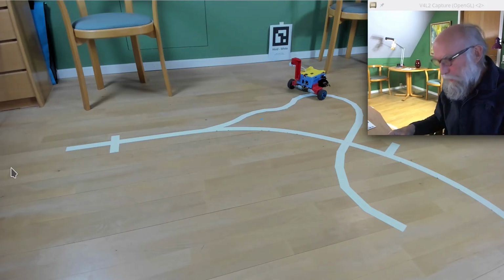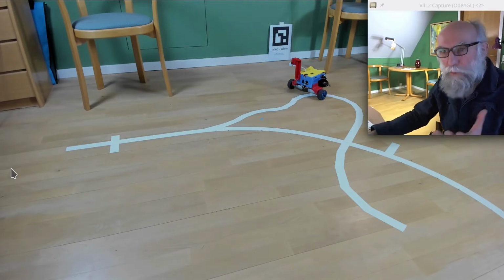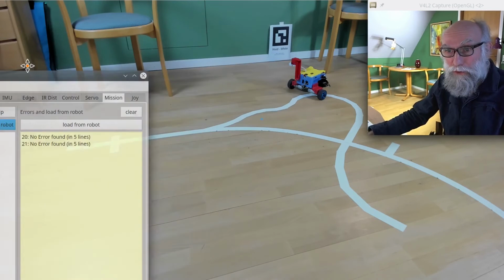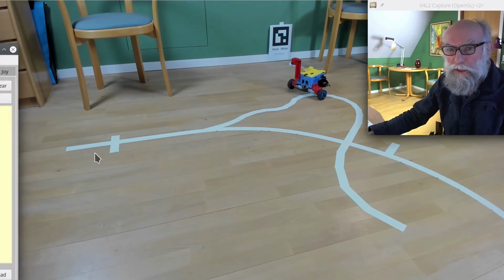The LED turns off once we have finished the line, so we must have finished the mission here. That means that with these control settings, we cannot go 0.4 meters per second, at least when it's so curved like this. We can try following the other side of the line, which is much more smooth.